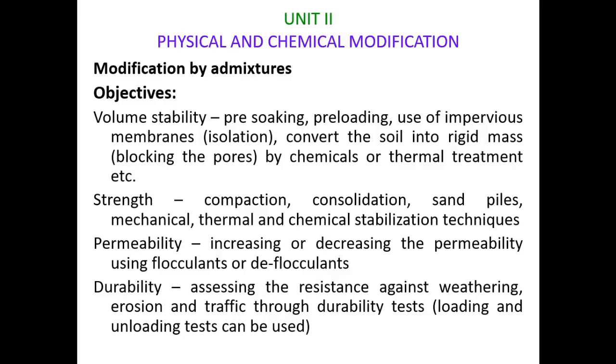Let's discuss the next soil property, that is durability. Durability of soil is its resistance against weathering process, erosion and traffic. The durability of soil is important for the design of roads, bridges, drainage ways, etc., as poor durability leads to high maintenance cost. In stabilized soil, the poor durability is mainly due to wrong choice of stabilizer, insufficient stabilizer, or inadequate water or chemical resistance of soil.